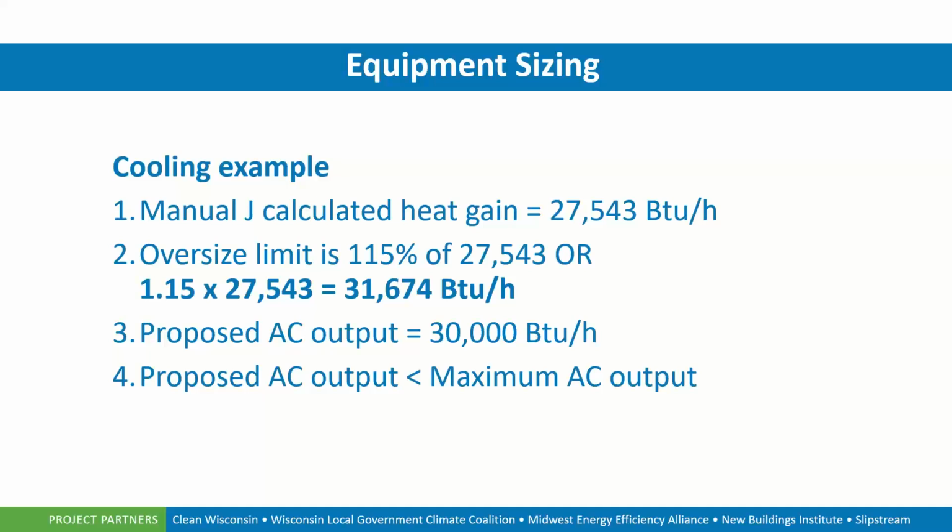Now cooling typically, in case you didn't know, is related to tons. One ton of cooling is equivalent to about 12,000 BTU per hour. Excuse me. So residential equipment is typically 1.5, 2, 2.5, 3, 3.5, 4, and then 5 tons as the common sizes.